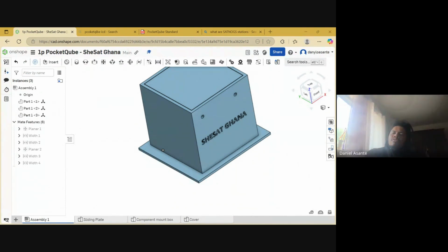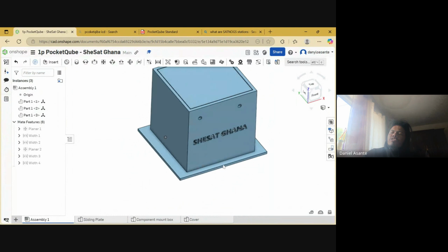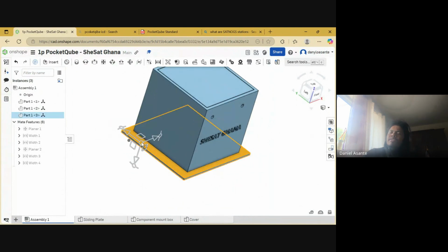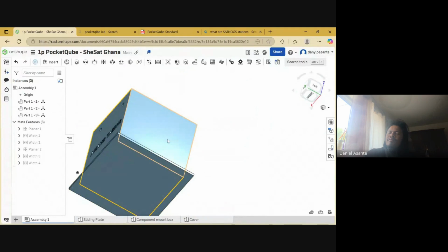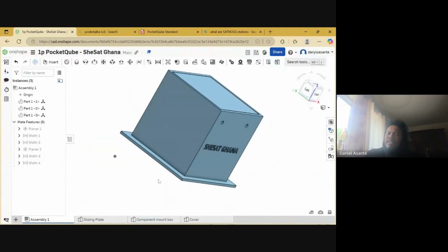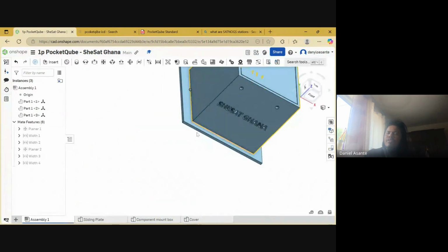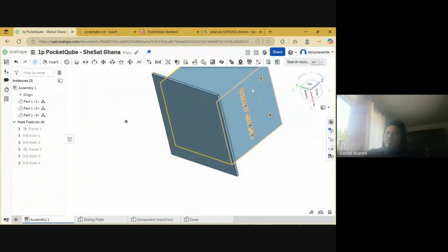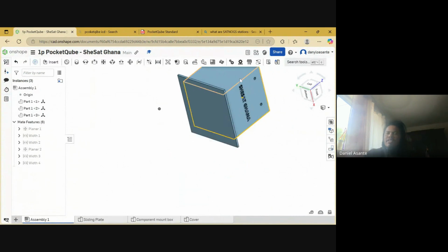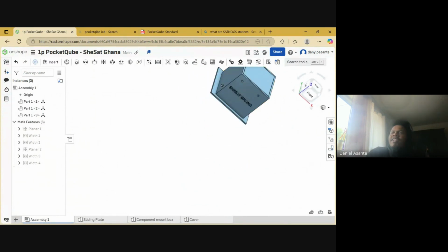But also wait, before we do that, I just wanted to point something out. The sliding plates you see here are also not mechanically mounted; they're just floating beneath it. So when you are making it, you need to make some holes beneath it. You need to think of a way to mechanically mount this to this by making a hole here, maybe a hole also on the cube to attach it here. So just remember.